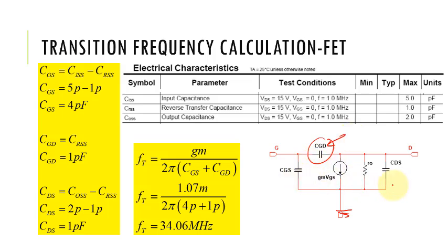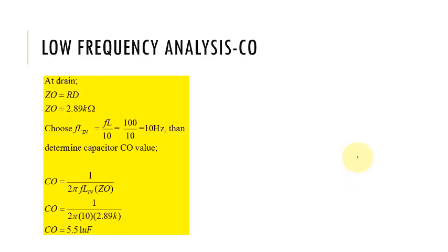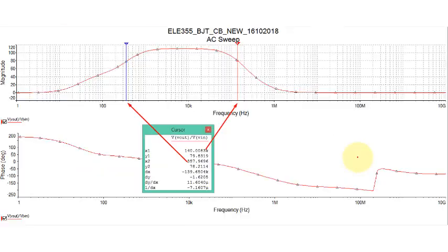And we have another two capacitors, CGS and CDS, which are connected from our input to the ground, and output to the ground. This capacitor we need to transfer by using the Miller concept like this. So we name this one C Miller in, and another capacitor here C Miller out. So we apply this method.